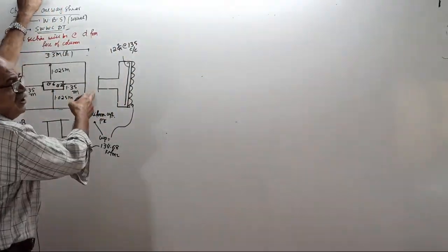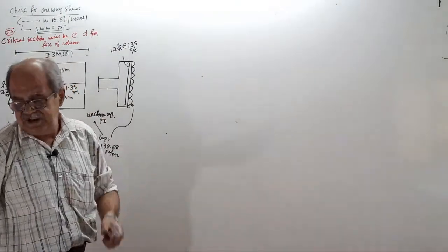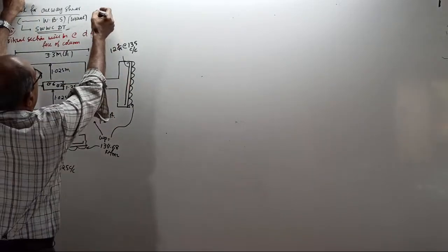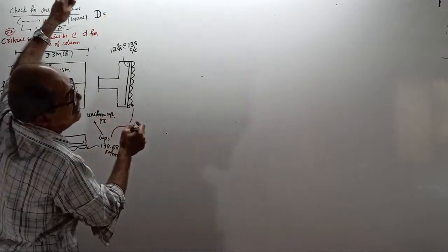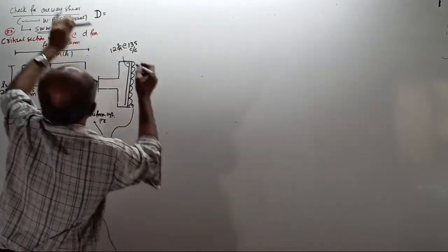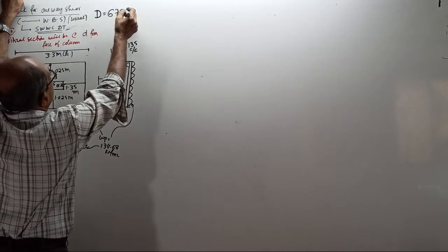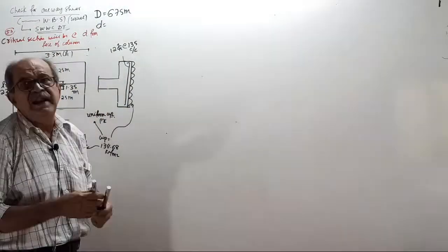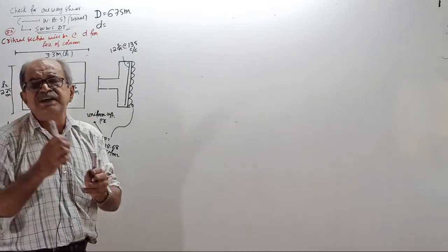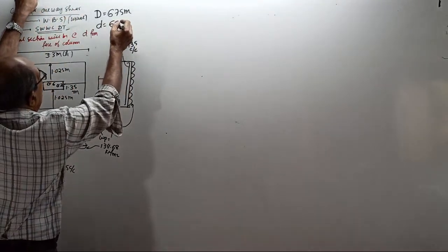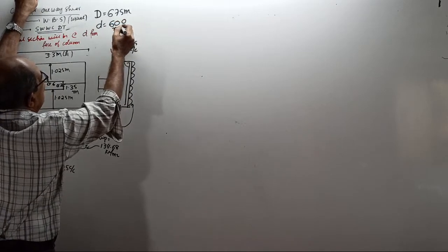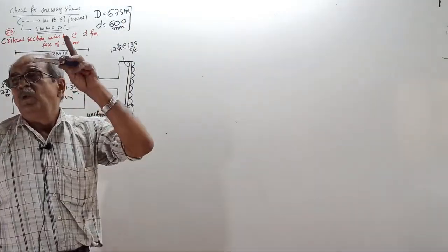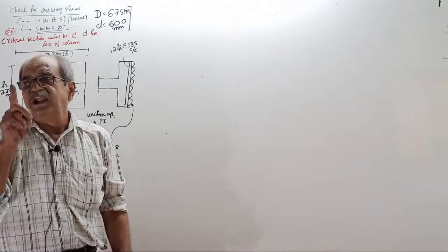Okay, now come back here, this question. Now you are checking for one-way shear. For our slab, if I remember, I made a note there, our capital D was 675 millimeter, and small d is actually different for this bar and this bar. For the safer side, we considered constant d, that is the lesser d, 600. Actually 601 came, 600 will do. Why? One rupee lesser we take, safer. These all I told you earlier. Which is advantageous, you consider lesser, safe.